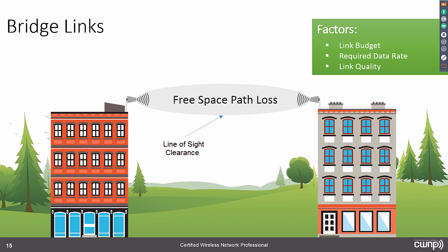Since they travel at this fixed speed, what we can change is how we're manipulating them to represent bits and how we're sending our bits. Are we sending more actual data bits and fewer redundant bits, or are we sending more redundant bits and fewer actual data bits? That's the coding part, and then the modulation is how we're actually manipulating the wave to represent bits so that we can represent 2 bits or 6 bits or more depending on how we're modulating this information. So the data rates are fixed, meaning there are specific data rates that are supported.